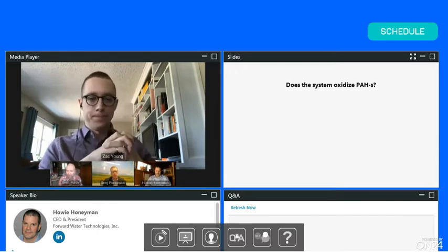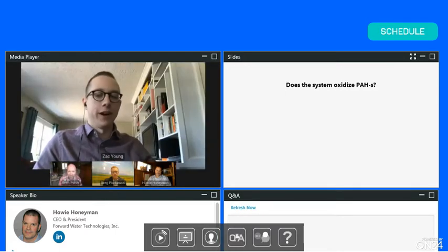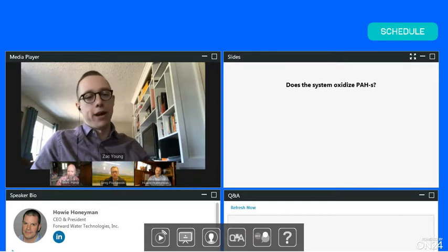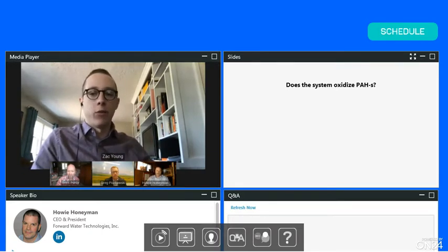Okay. Question, whether you've tested for the presence of PAHs in the system when you've been doing the trials, and whether there's any potential for oxidation and reduction. Yeah, absolutely applicable there as well. In fact, there are aromatic rings that we're treating in the naphthenic acids themselves. So yeah, PAHs are certainly addressable by a photocatalytic AOP. One thing that may be of interest to people in the chemistry side is that we're generating a mix of oxidants, so not only hydroxyl radicals, but also superoxide radicals from dissolved oxygen in the water. So there actually are some reaction pathways that are particularly well suited to this application. And so, absolutely treatable.